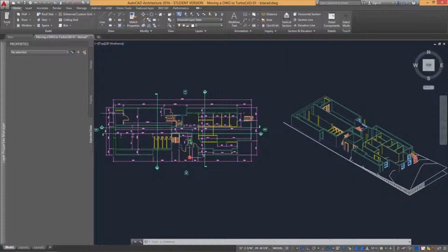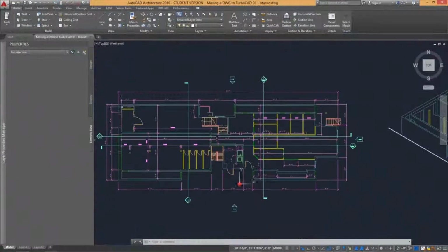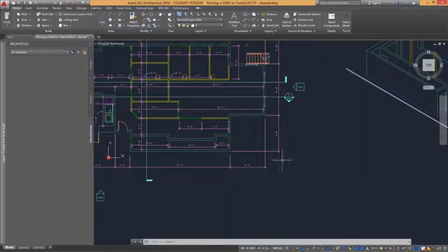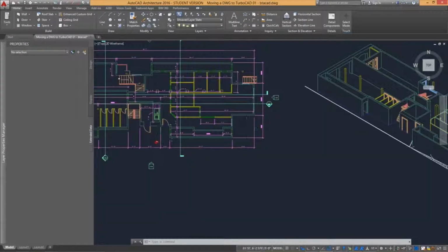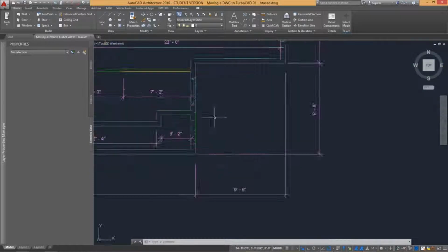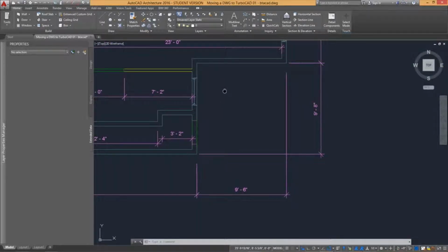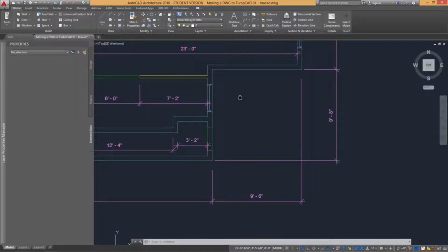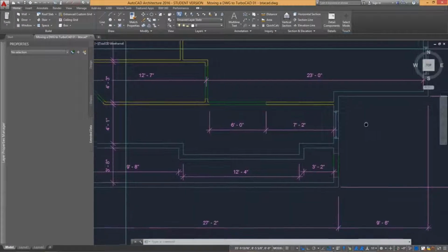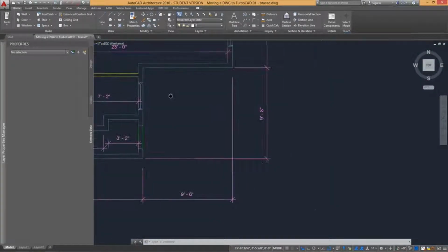Switching back to AutoCAD, we can see there is similar functionality where you position the mouse at the point of interest and roll your wheel mouse forward and back. Once you're in a sufficient zoom magnification, it is possible to pan around the drawing by clicking and holding the wheel mouse button and then dragging to adjust the view.